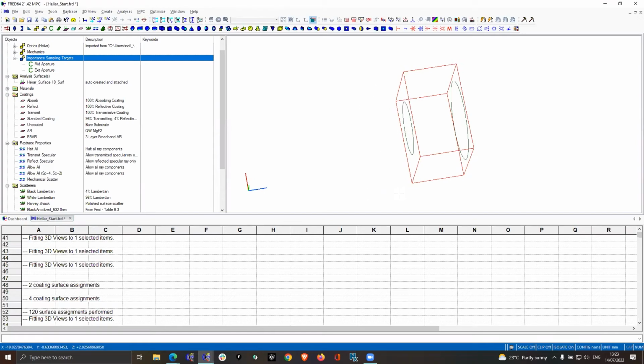important sampling that says that the surfaces at the front of the optical system here that can essentially see this aperture or this opening will preferentially scatter rays into this opening. And similarly, in the second half of the optical system, the surfaces that face this opening will also scatter light preferentially through that opening. Okay, so those are the 2 targets that we're going to choose, and anything other than that is just going to be around specular. Okay, so